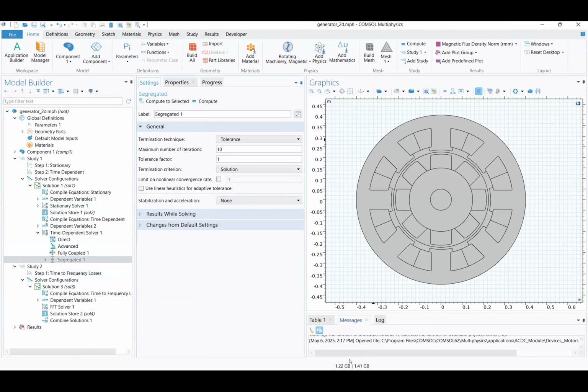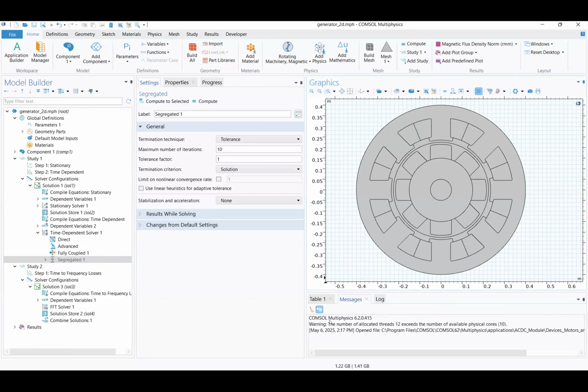Yes, well, it's about interpolation in the elements. Instead of using quadratic interpolation, they suggest we use a linear interpolation. We always use linear interpolation. I don't know who is using quadratic. By default, it is quadratic. If you allow me to share my computer, let me show you here.